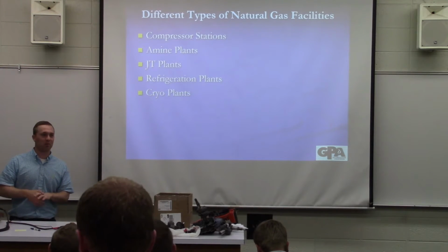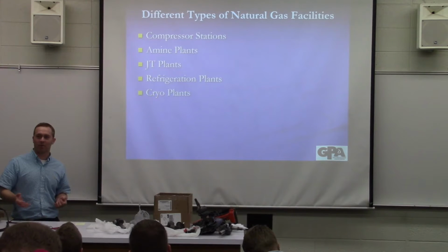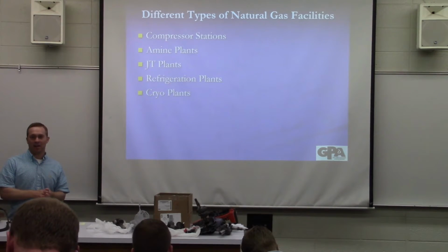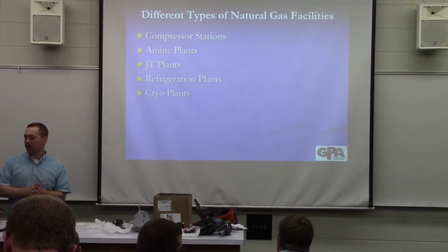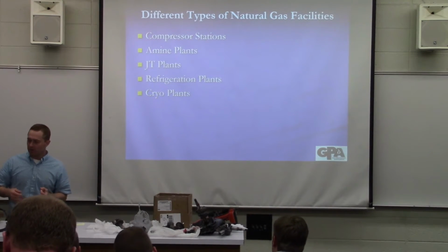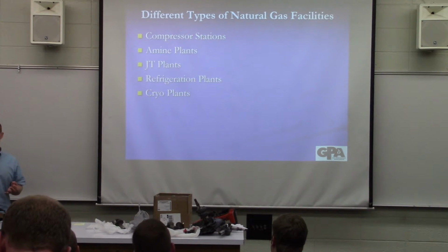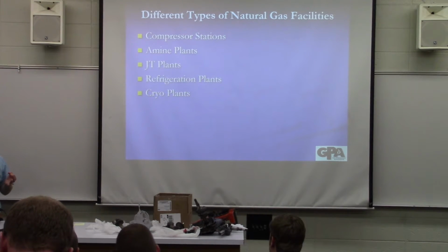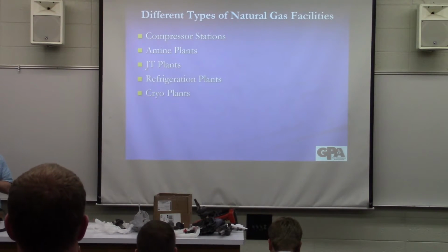Natural gas processing is really pretty simple. You get the gas cold, right? It's just thermodynamics. You want these components to drop out as liquids, so you get the gas cold. And there's a few ways you do that. So a JT plant, JT stands for Joule Thomson. Anybody want to dazzle us all and tell us what the Joule Thomson effect is? Anybody want to take a shot at that?